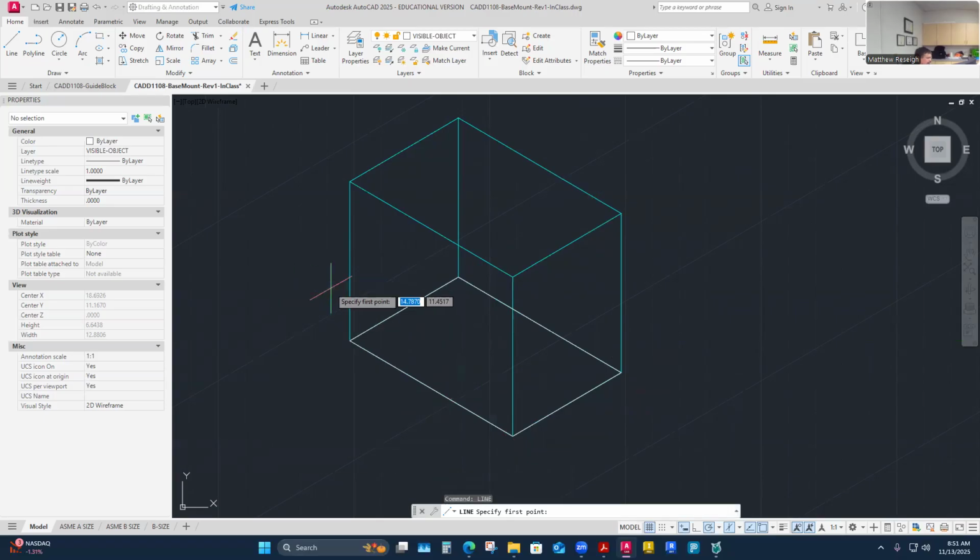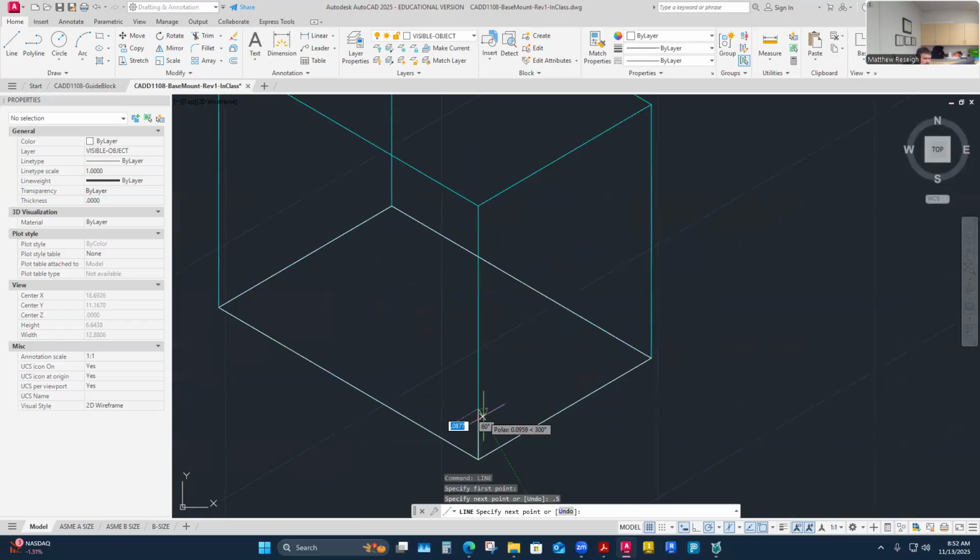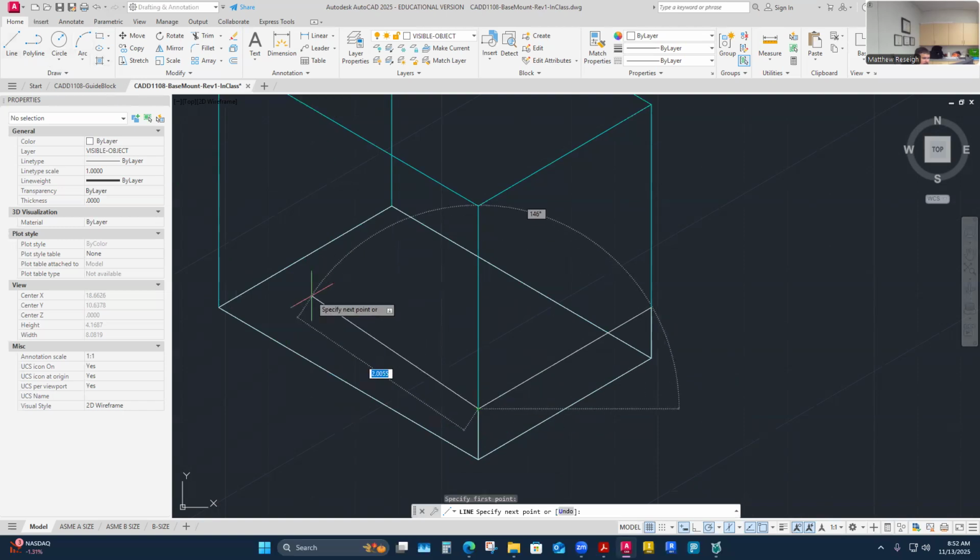And then it goes up. It's a 1/2 inch thick plate, so it's 1/2 inch up here, 0.5. I'm just going to start on one of the corners. That's 0.5 up. I drew that line, 0.5. Then I'm going to come across and back down. That's the plate thickness that I would see here. So really I can just draw this back now to the back.